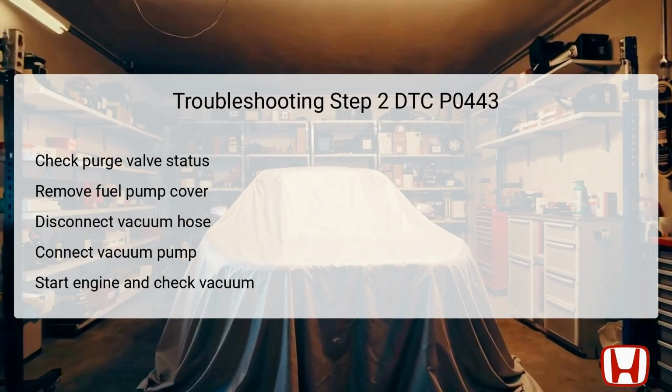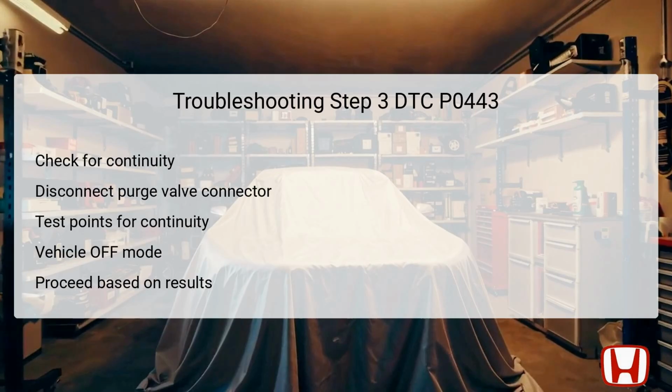If vacuum is detected, it indicates that the valve is stuck open, leading to a clear indication of malfunction. If no vacuum is noted, the valve is likely stuck closed, compelling you to follow the next diagnostic steps to ascertain the underlying issue.